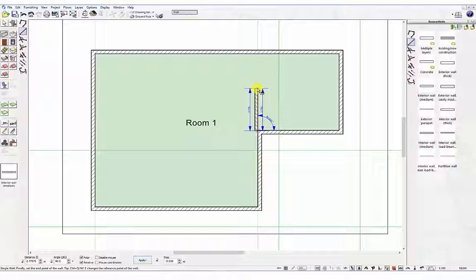Before placing walls in position, use the key combination Ctrl and W to toggle between the wall edges and wall axis. This lets you define which wall edge to place in relation to the reference point. For example, the inside edge of wall, center line of wall, or outside edge of wall. Try pressing this key combination a few times to see the effect on screen. Use Ctrl and W to follow the inside edge of the vertical wall below.